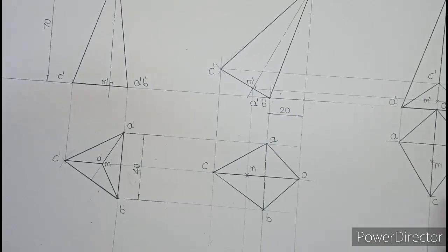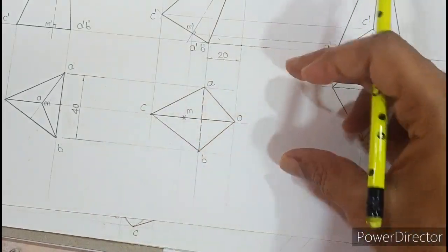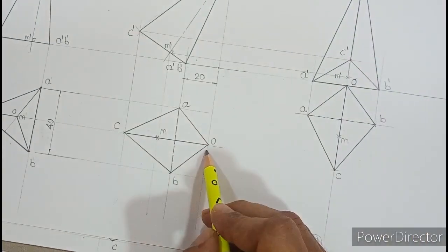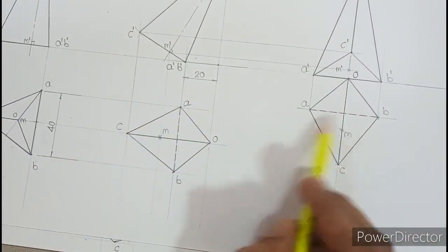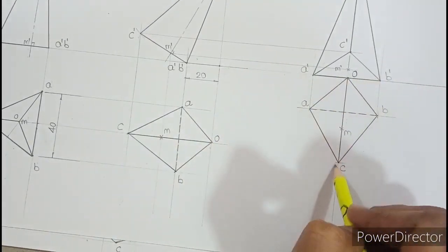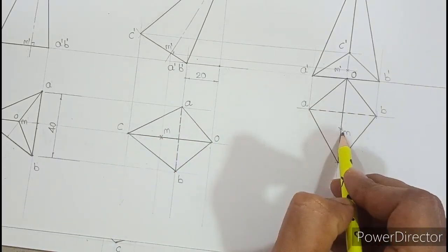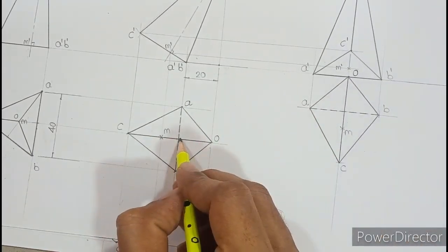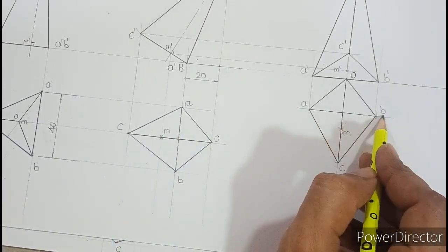So to turn in this direction by 90 degrees so that the base edge becomes parallel, and apex should touch my hand. That you can see only from top view. So in the next stage what we have done is, this diagram we have turned by 90 degrees. So first we have made this point O to rest on XY. So fifth diagram is here. So make this point O to rest on XY. Draw a line perpendicular to XY. Take the distance from O to hidden line till M. Then if you look at this point, take half of AB in the compass and cut left and right, and reproduce the same diagram.